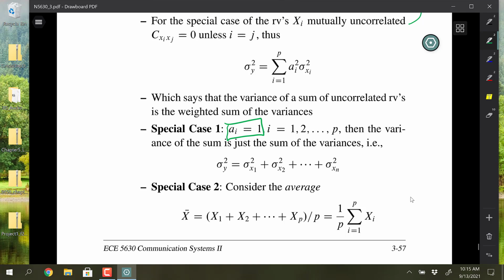But a communications engineer would say, well, I can cope with that to a certain extent because I don't expect all channels to be really, really bad, and the math will work out such that if one channel is really bad, you just won't use that one at all, you use the better ones. And so what's an example? Is there a wireless hub in this room? I don't see one. There's maybe one out in the hallway, but you're familiar with wireless hubs in your house. You generally have two-channel diversity combining. So that's just doing some maximal ratio between those two sources.